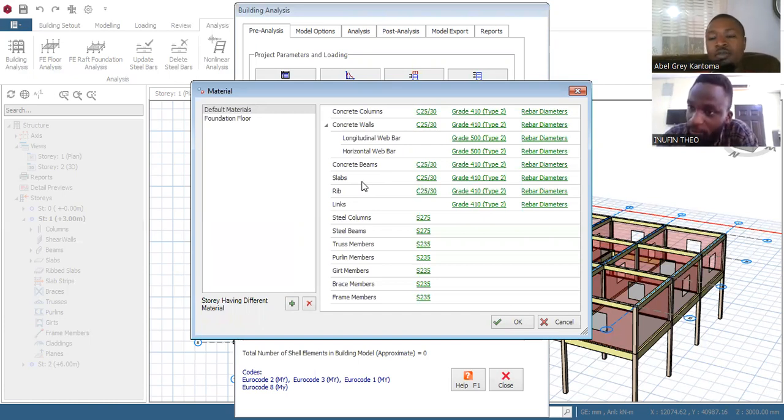They just call an iron bender, who will just say, this is how we used to do it, using his past experience. They don't know that buildings are not the same. The same reinforcement and spacing you use for a span of 3 meters, you still want to use for a span of 6 meters. So you are definitely most likely going to have issues.